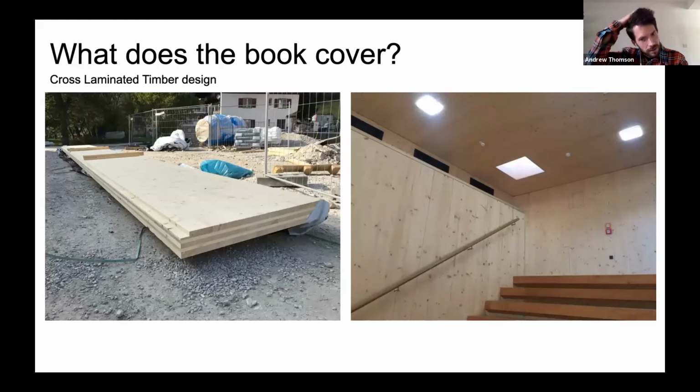I think cross-laminated timber is an amazing material and you can do amazing things with it, but it is not by any means a sort of panacea to all our problems. It's a very hungry material for volume of timber, but it has a place. And I think from a design point of view, there is a gap in knowledge there. And so I do think the chapter that James predominantly wrote on cross-laminated timber design is really valuable. It really demystifies what is a little bit of an unusual material from a design point of view.